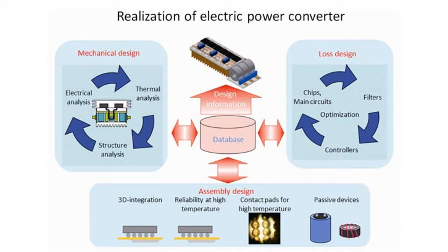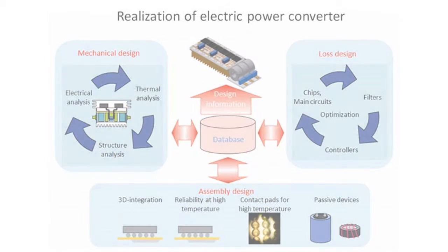A very interesting topic is a comparison of analog and switch converters. Switch converters are seen as devices with high efficiency, smaller dimensions, and high power in comparison to linear converters. They also do not need a complex cooling system. But these devices are more complex than linear ones and cause corrugated output voltage, which prevents the use of certain precise applications. Linear converters are nowadays most often used for lower powers as stabilizers of different electronic components. Here are some characteristics of both groups.